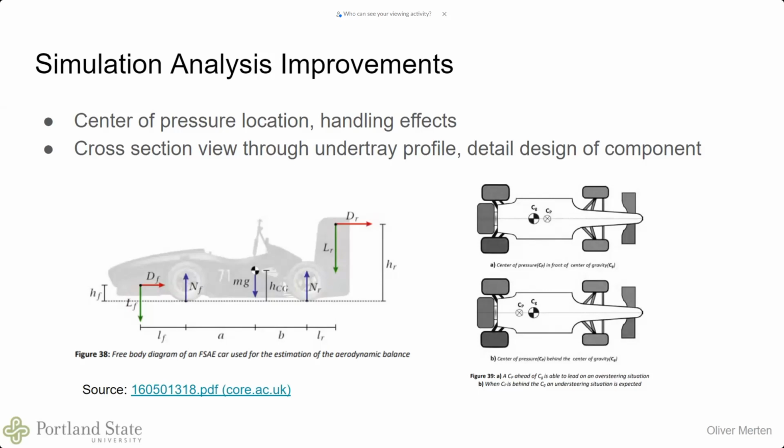So along straightaways and, in our case, whenever the vehicle is moving, you're going to get a force. But the faster you go, the greater the pressure distribution will be, and the greater effect that center of pressure location will have on your handling. And so because our vehicle has understeer as the suspension is currently designed, we would want to position the center of pressure in a place that could counteract that. Because ideally we'd have kind of a neutral steer vehicle.